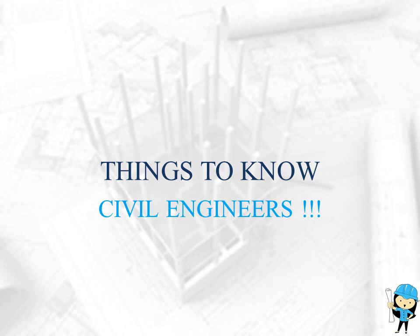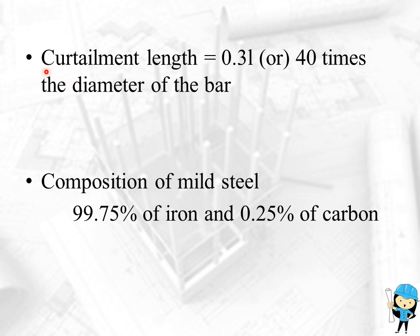Today we are going to see some important facts to know for all civil engineers. Curtailment length. Curtailment is restricting the bar length, that is reinforcement length, according to the Ast provided. The curtailment length should be 0.3 L, where L is the length of the beam or the element, or 40 times the diameter of the bar.